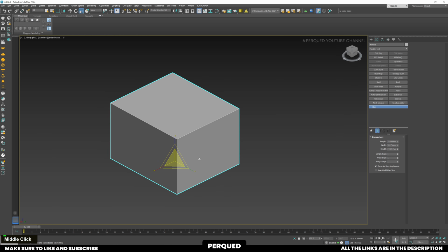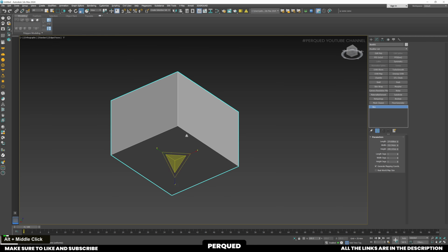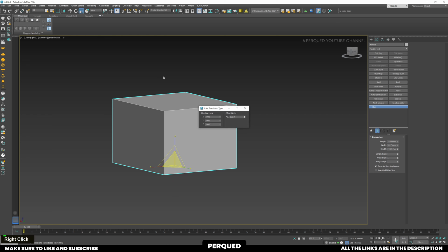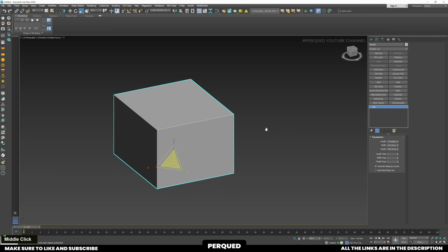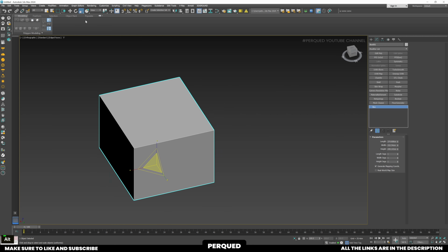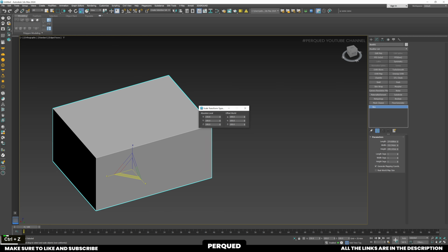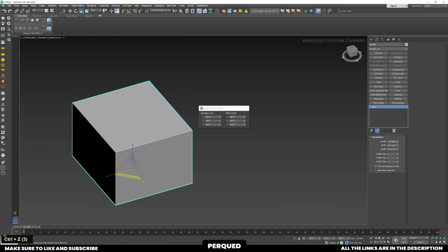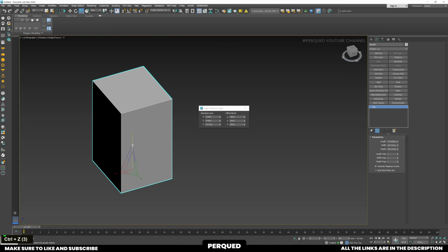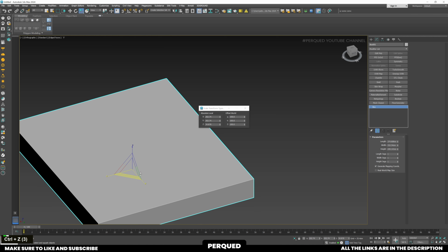The Scale tool also has a toggle. If you press R multiple times or hold left click on Scale, you'll get a bunch of other options to scale your objects differently. Also, if you right click on any of these, it'll show you a dialog box to manually put values for move, rotate, or scale. It has uniform, non-uniform, or squash options to choose from. Uniform will make your object scale evenly from here. Non-uniform will have the option to scale from X, Y, and Z independently. Squash will make your object scale in any direction, but it'll maintain the object's total area.